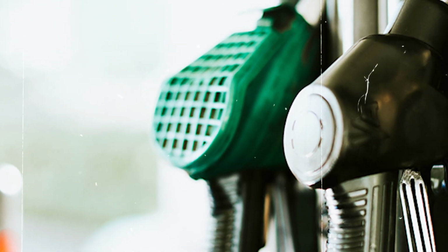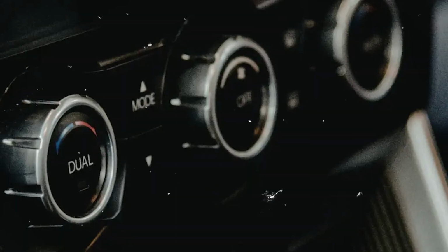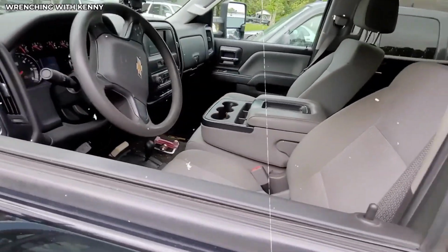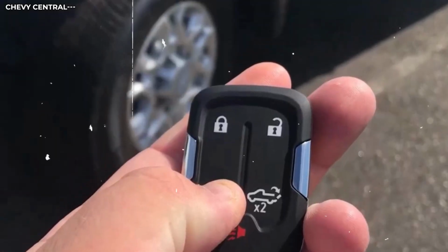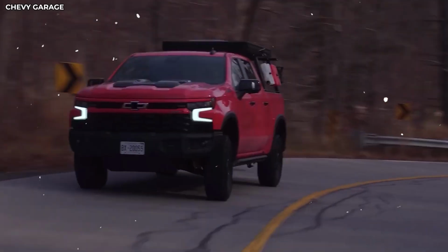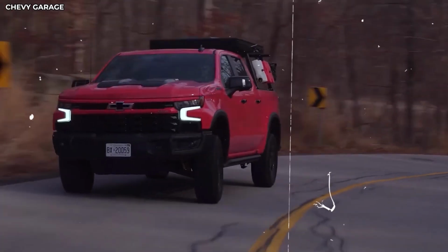Fourth, never reset adaptive learning if you have existing check engine lights or transmission fault codes. Fix those problems first before clearing learned data. Resetting with active fault codes can make diagnosis more difficult and potentially cause additional problems.